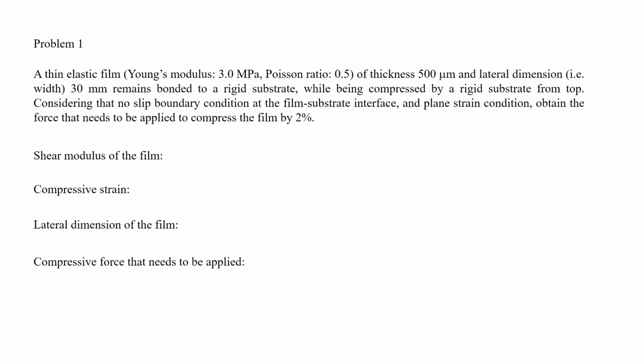A thin elastic film, Young's modulus 3 megapascal, Poisson ratio 0.5, thickness 500 micron. So, Young's modulus is 3 megapascal. The shear modulus mu we know is E over 2 into (1 plus sigma), and therefore it is 1 megapascal here. Thickness 500 micron.